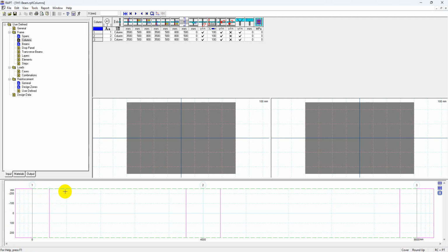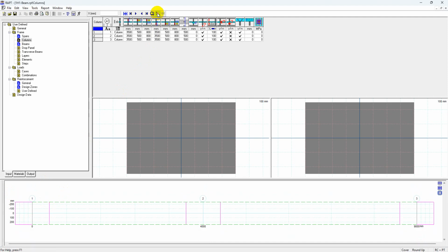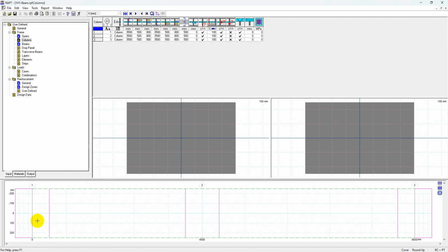So what should we do? Make sure that we inspect the scale and also the dimension provided. We go to scale or no scale. We click on this. We see that when we scale this picture, the beam is connected to the strong axis of the column. But if we do not scale, by bare eye, without looking at this dimension, we may think that the beam connects to the weak axis of the column. So always be cautious when we provide the input of the column here.